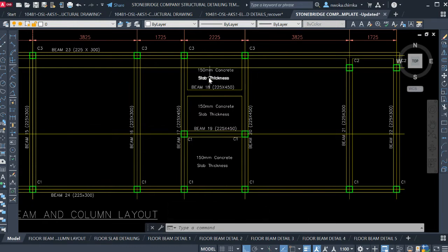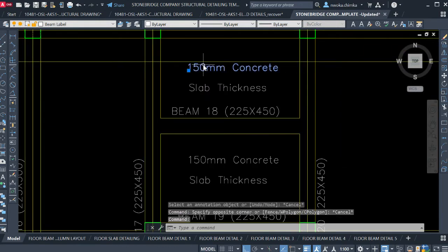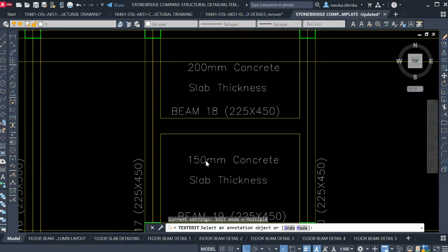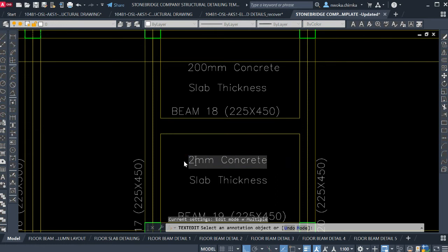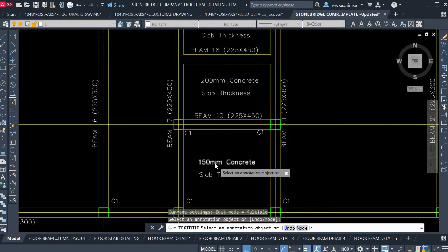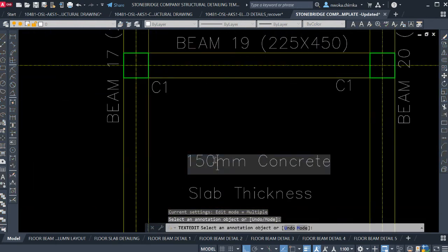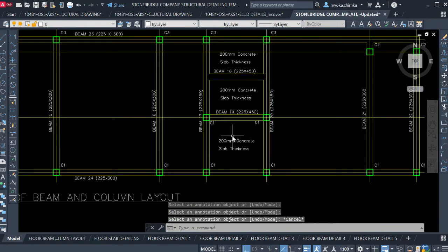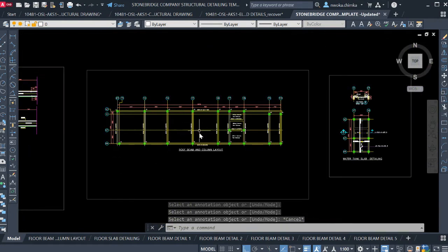As you can see here, that's why it has a slab. The slab here is 200, not 150. This is to be 200, not 150. Okay, this 200 millimeter slab will be able to carry the water tank. Okay, 200.